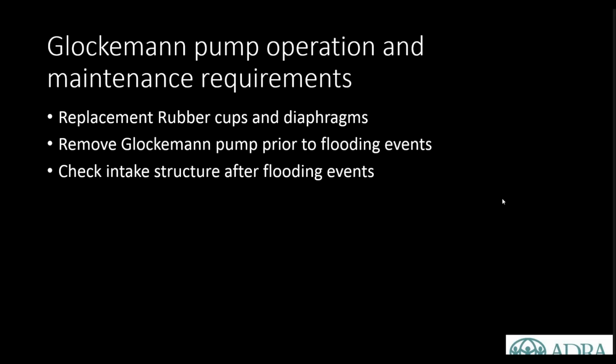Yes, it would actually be quite a good solution for them, because a canal usually has quite a low hydraulic grade, and these wouldn't require too much extra drop to make them work. You could even just drop them into the canal, especially if there's no top on the canal.